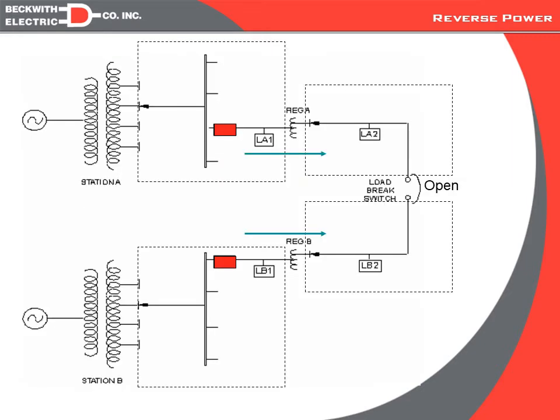But now if we have a fault, so this is again our normal mode, open switch, you can see this regulator is regulating this zone with the power flow going in this direction. This regulator is regulating this zone with it going in this. And then the LTC is regulating up to the regulators if we have it coordinated correctly. And in actuality, it's going all the way down to here, because if the whole voltage is low, it's going to correct everything.